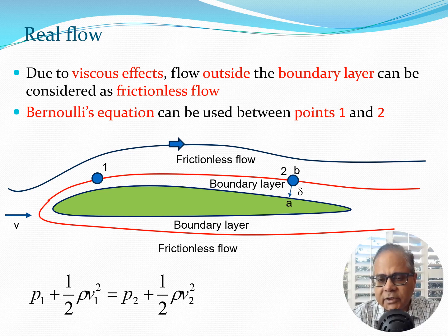Now, this is a major simplification in fluid dynamics, and it does tell you why all the frictionless flow fluid mechanics which you study is useful, because all you have to do is apply those equations to the points which are outside the boundary layer, and inside the boundary layer you have to have some different philosophies going on.